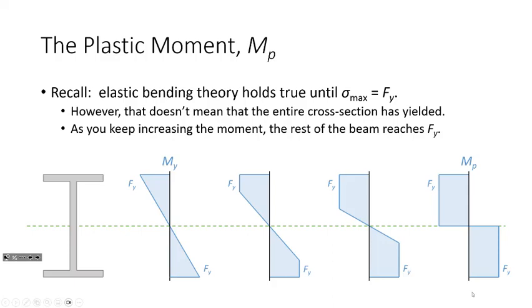So if we're talking about the beams in the building, and we're going to talk a little bit more about that on Friday, being able to characterize that is a longer discussion, because what we need to do is take each of those elements and ask what are the bracing conditions for those elements. Some of them are continuously braced, some of them are discretely braced. So their behavior is different depending upon that. You'll see what I mean when we get into the lecture, but the short answer could be that beams might be continuously braced, but girders might be discretely braced.